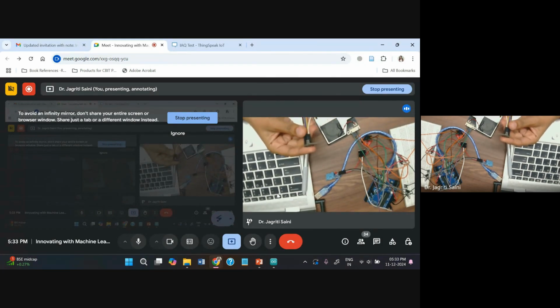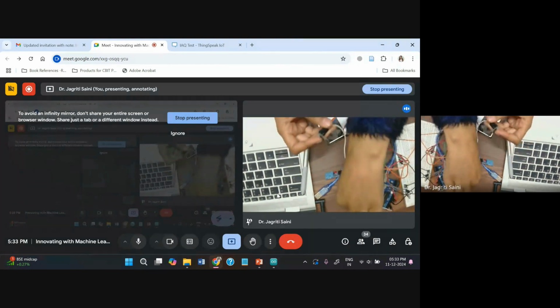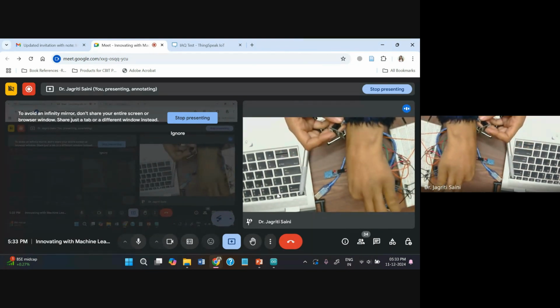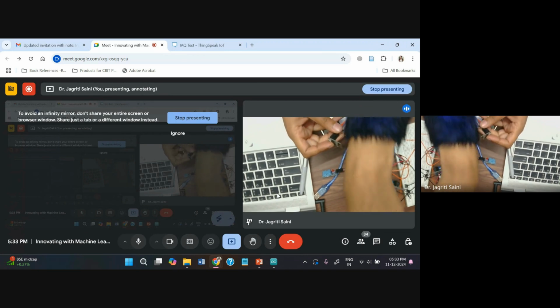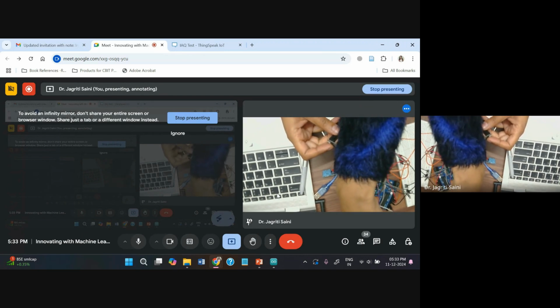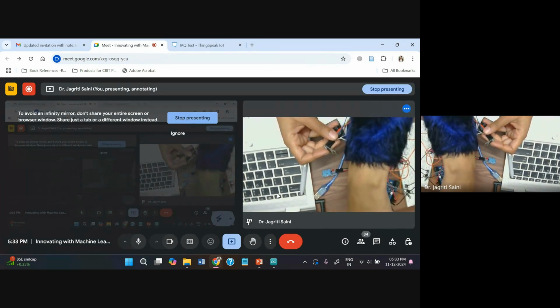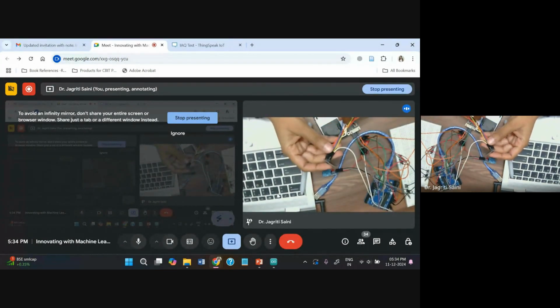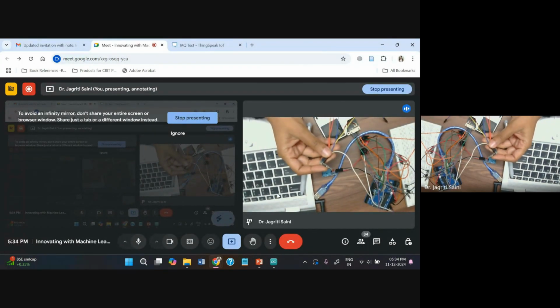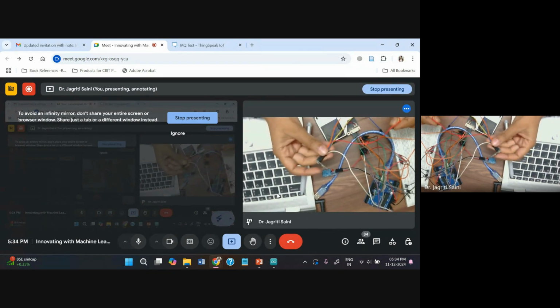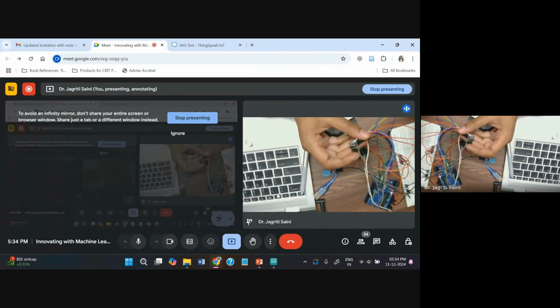And then first of all I'll connect the ground terminal of this ESP board, and I'll be using a separate ground for safety reasons on this particular. So I'm taking it from the digital section of my Arduino. Then I'll be taking up the VCC. I'm using this orange and red wire. Since this particular gateway works on 3.3 volts, accordingly I'll be taking this 3.3 volt section from the hardware.